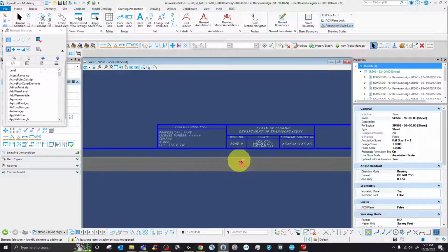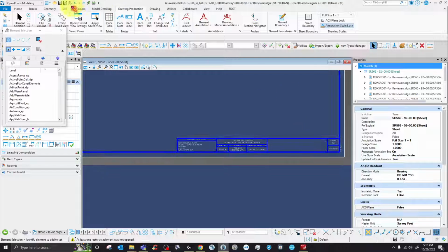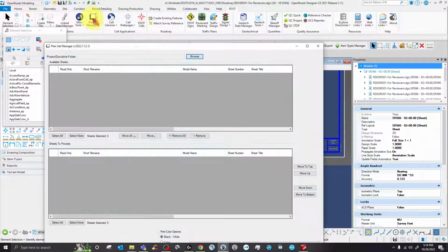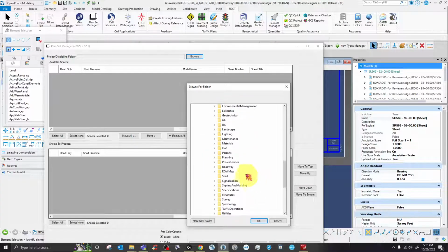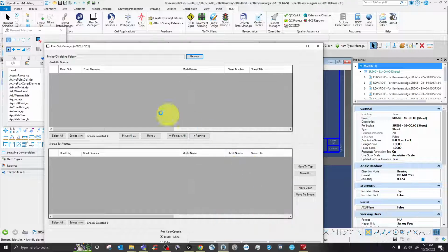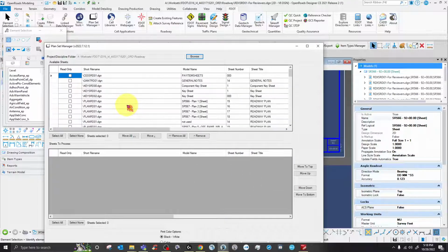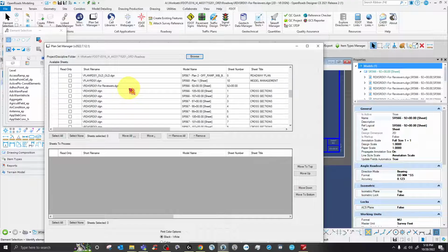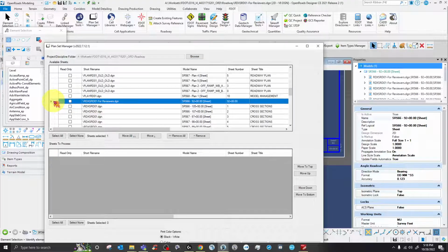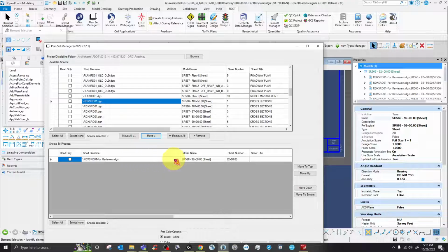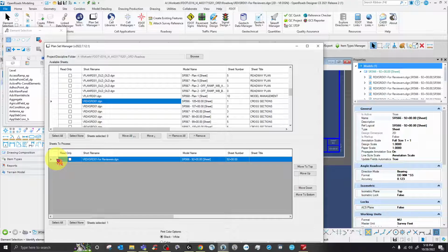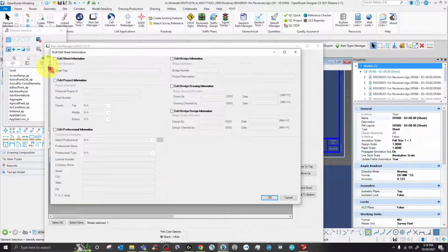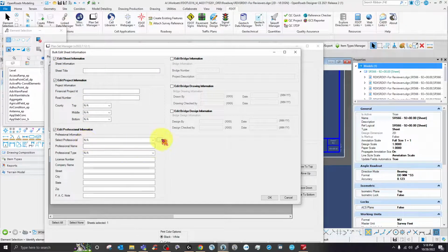And just for my babies out there who don't know how to do the labelings, you can just fire up this amazing tool that DOT created, go to your project and go where you have your roadway and just click OK. Then scroll down to the cross section for the reviewer. We only have one sheet, easy breezy. Select it, hold right click, update bulk. Come here, select this, select this, select this.